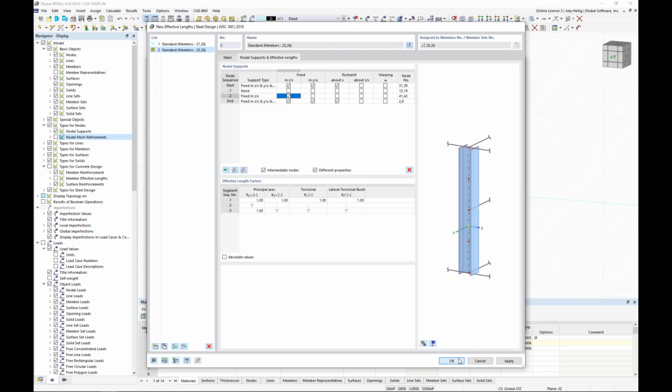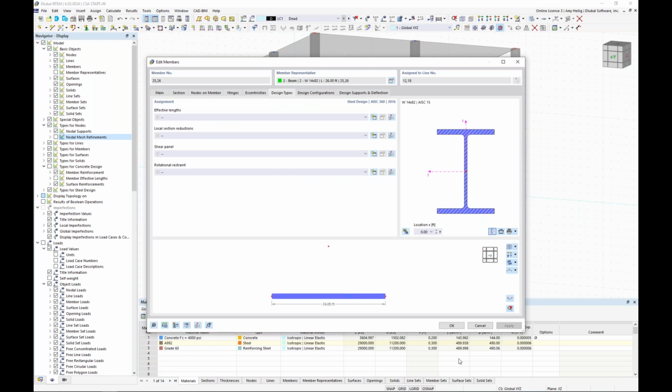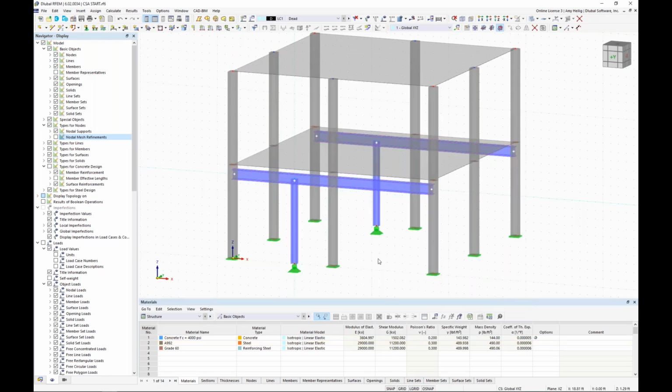Okay, so that takes care of the unbraced lengths, which will again come into play a little bit later on for our actual steel design according to the AISC. The final topic here related to this first story is currently this slab element is entirely connected to this steel beam. So full force transmission, full moment transition between these two elements.